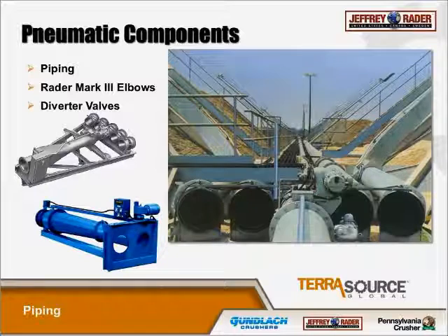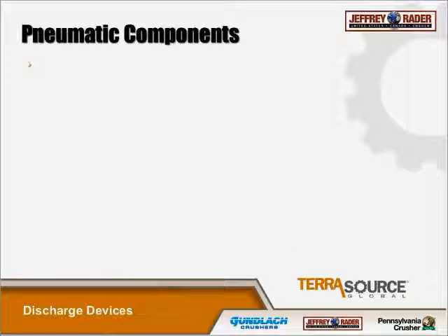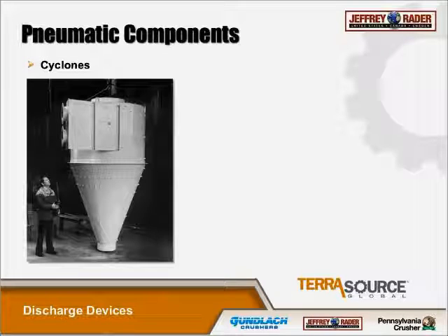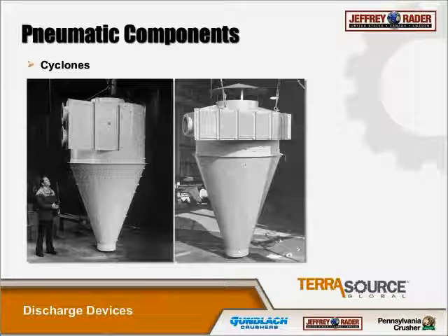As with the elbows, these valves also include low impact angles, which help minimize the wear, minimize the pressure drop, and minimize horsepower. These are going to be important themes throughout pneumatic conveying systems.